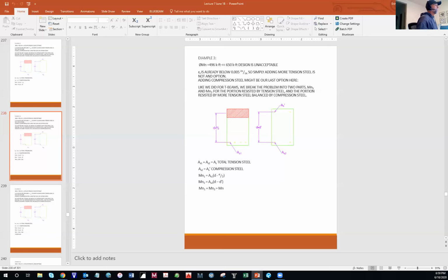That beam that has the positive moments and the negative moments, I didn't tell you how deep the beam is. That's part of what you have to design. So here's a trick. Whichever is greater, the positive moment or the negative moment in absolute values, whichever one is more kip feet, that moment is going to dictate how deep the beam becomes. And then the other moment is going to be smaller.